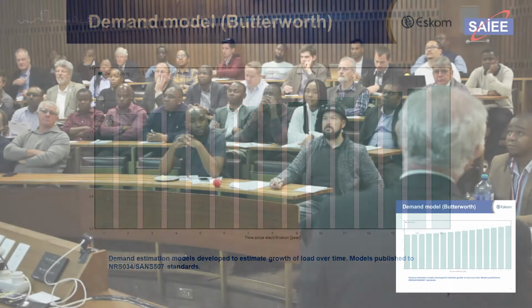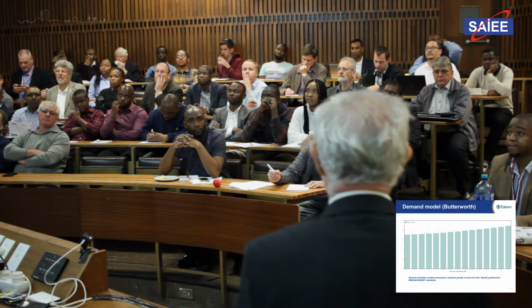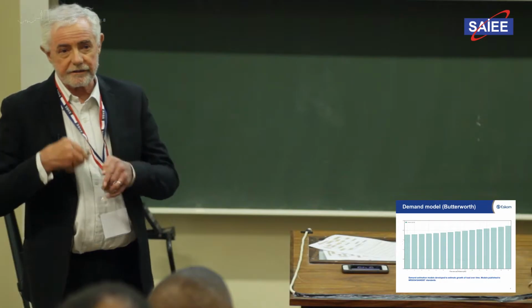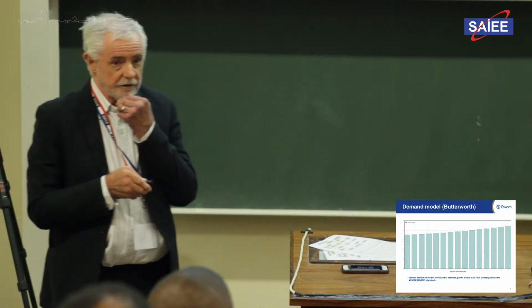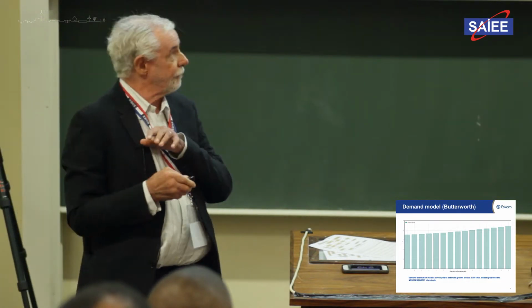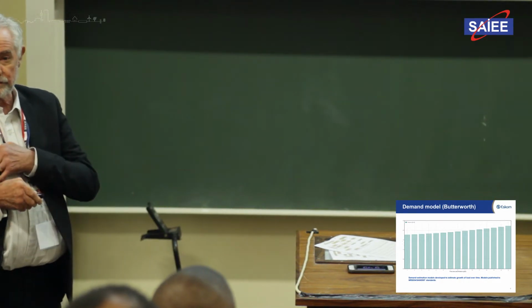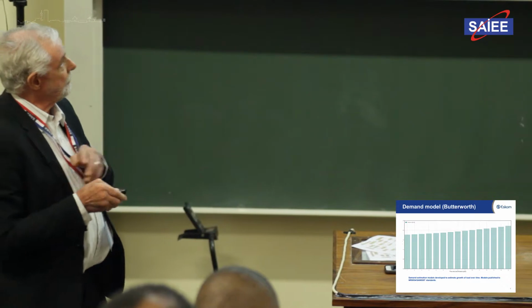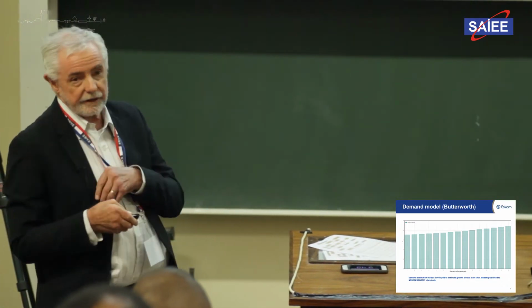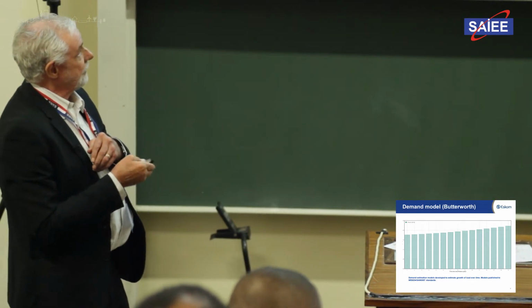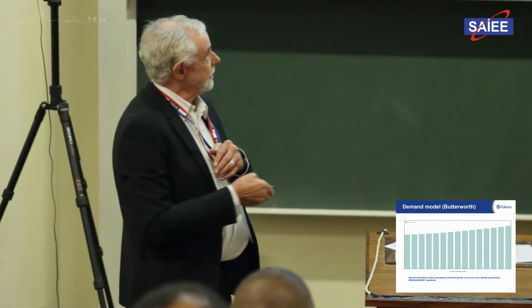But the way to design the networks then was to actually have a robust network so that you can expand without a lot of extra cost. So you plan your final design, and then you add in as your load grows. You can go from 50 kVA to 100 kVA, 315s, 200s on the pole top, going forward for your transformer zones.